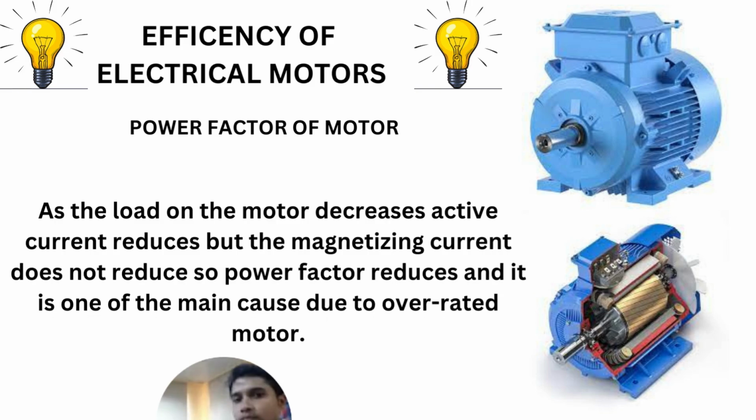Now we will discuss how the loading of the motor affects the power factor of the motor. As the load of the motor reduces, the active current of the motor reduces, but the reactive current, which is required to maintain the magnetizing current of the motor, doesn't get reduced. So the power factor gets reduced.